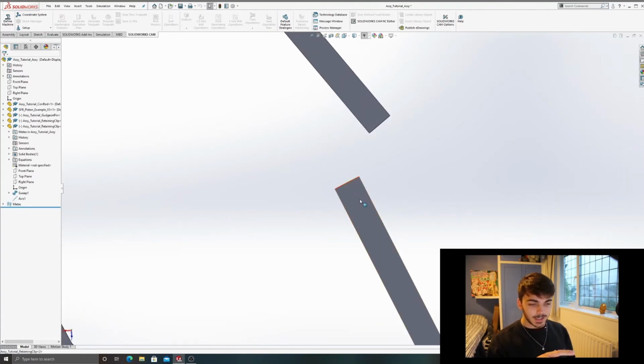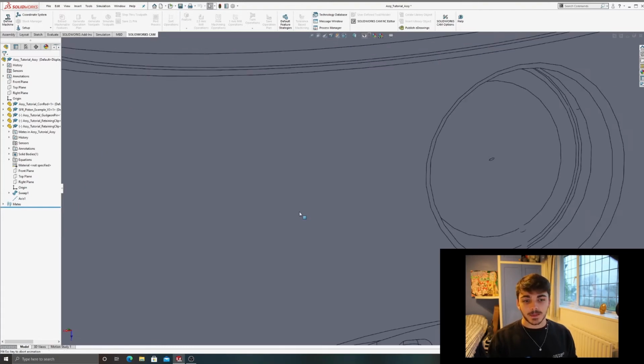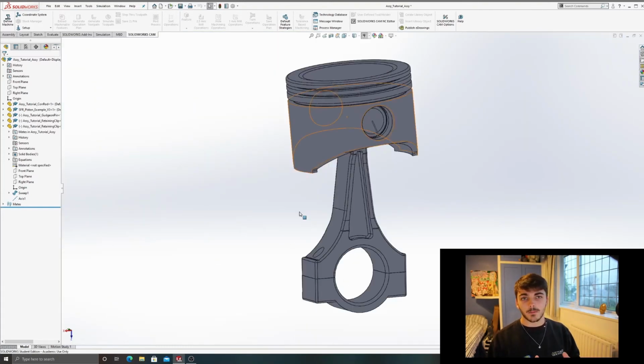If I don't do that, so for example around this retaining clip you can see there's just empty space. If I put my mouse there and try and rotate, I will completely lose any idea of where I am, and that's a real pain, especially if you're trying to do some complicated sketching, etc. But if you do that, there's an easy fix. Just press F, and F brings the whole part back into your display.